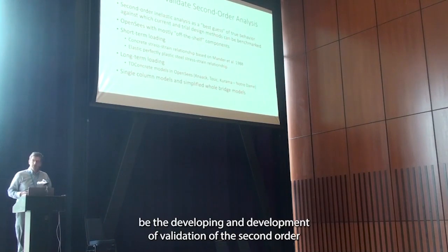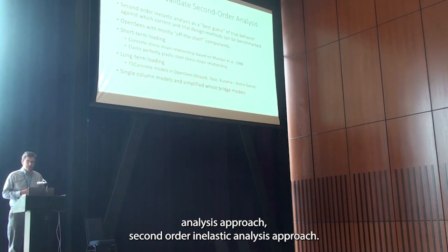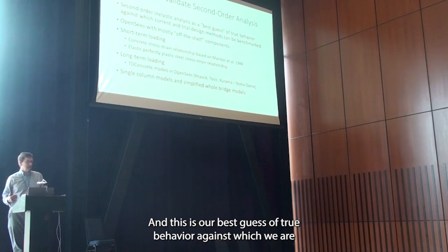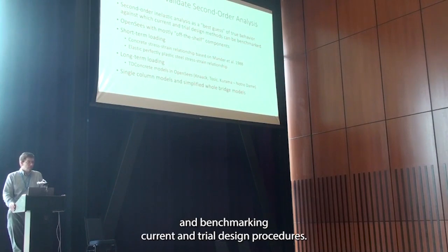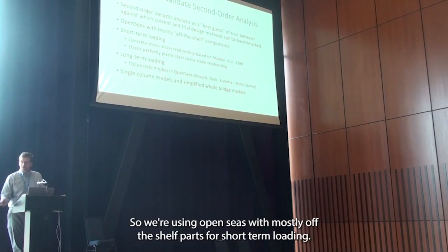So first would be the development and validation of a second-order inelastic analysis approach, and this is our best guess of true behavior against which we are evaluating and benchmarking current and trial design procedures. So we're using OpenSees with mostly off-the-shelf parts.